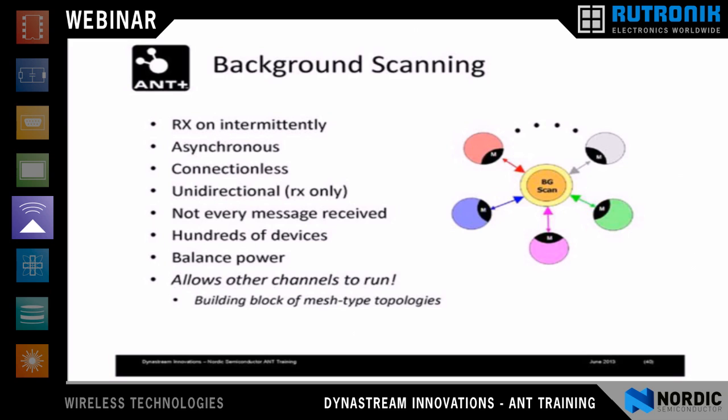Okay, and sometimes you may want to have existing independent channels alongside a synchronous or an asynchronous scanning method. So we've made a background scanning channel. What it does is it performs that same scan in more of a search duty cycle. So it's much lower power, probably in the 2.5 to 3 milliamps of average current, but it allows you to be able to have an independent connection.